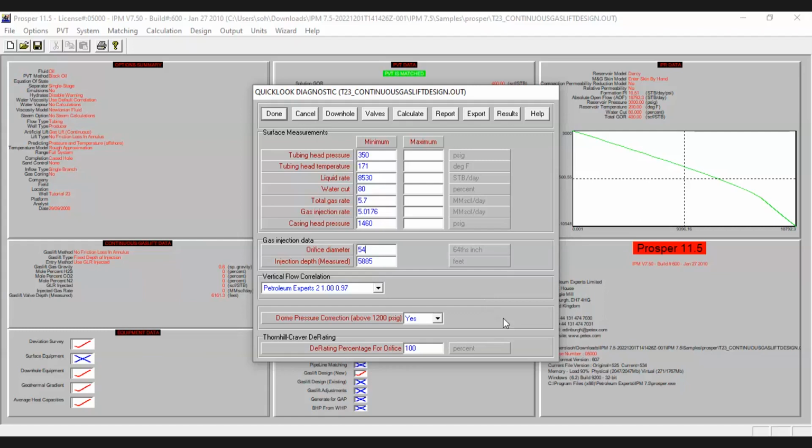This is the operating valve, right? The lowest valve that gas will be injected, right? Yes. Okay. So now, the original size of the orifice was how much? 32. Now it's 54, right? Yeah. Okay. Why did we increase the size?